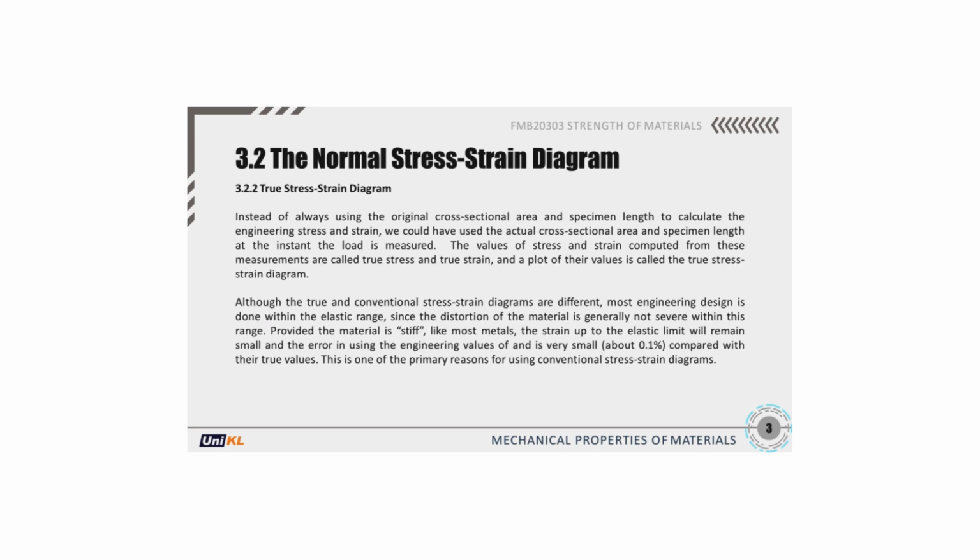True stress-strain uses the instantaneous area and length at load application. While the true and engineering curves differ, most design stays in the elastic region where strains are small and engineering values deviate by approximately 0.1%. Hence conventional diagrams are widely used.